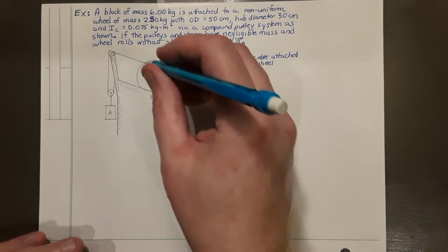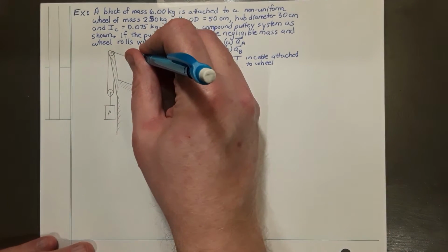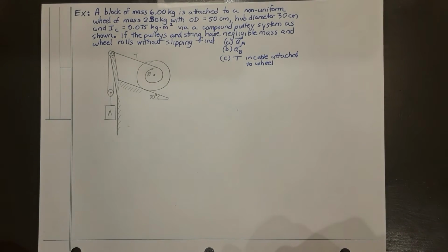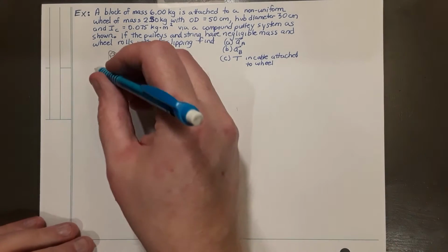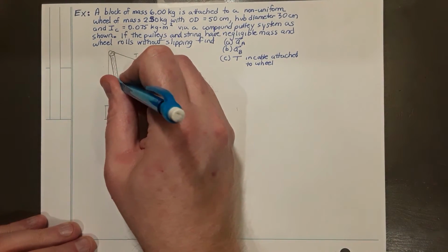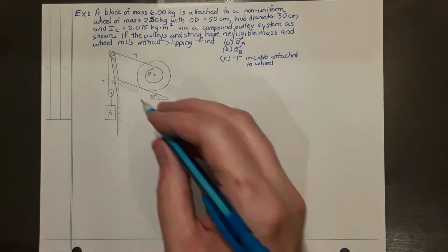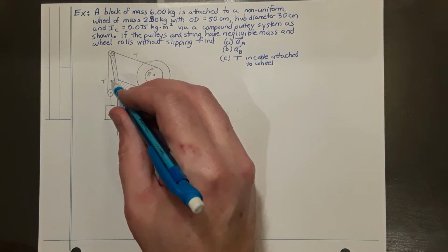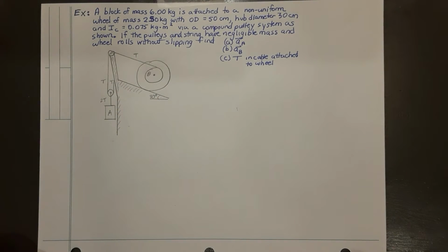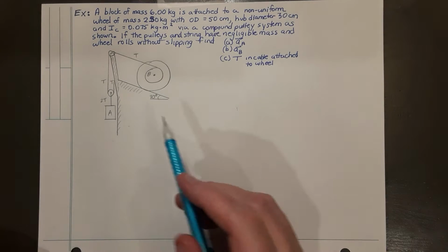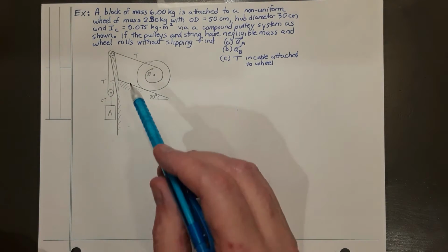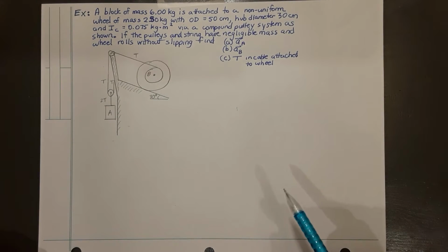And so first, using the compound pulley system, if we call this cable tension T, the tension in the cable attached to the wheel, that means then that both of those 2 cables that are on either side of the pulley both have tension T, which means we have tension 2T at that location, assuming that pulley has negligible mass. And so we have a 2-to-1 mechanical advantage with this pulley system.